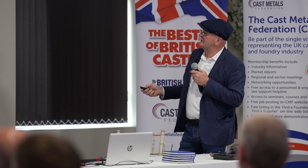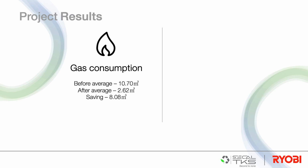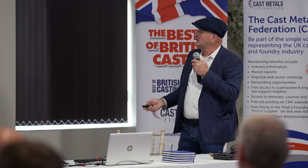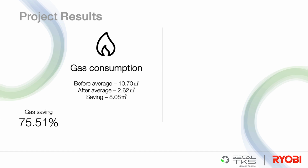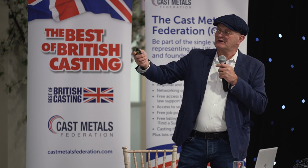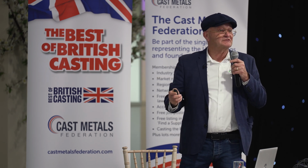But what we managed to achieve with this: we heated 3 ladles with the conventional burner and took the average, which was 10.7 meters cubed. With the emitter, we did the average, and it was 2.62 meters cubed. Now, obviously, the difference of that is 8.08, which gave us 75.51. That was categoric with that one, and that was signed off by ourselves and the client. There's no smoke and mirrors with this. It's actual.